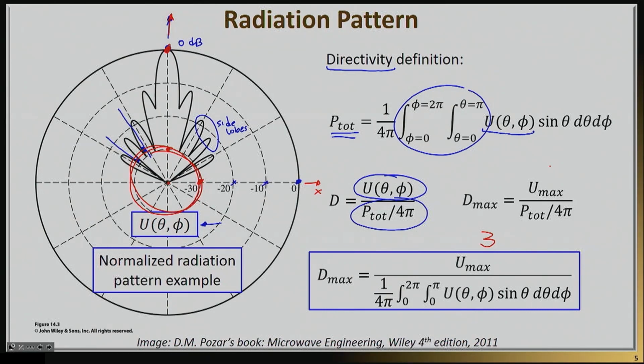So it's almost like a balloon. You squeeze a balloon in one direction, and it bursts out in the other direction. That's exactly what we want from antennas. There is no active amplification. It's literally a piece of metal with dielectric. But there is definitely a directionality involved here, which we try to capture through this definition of directivity.